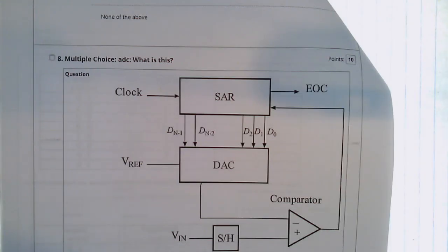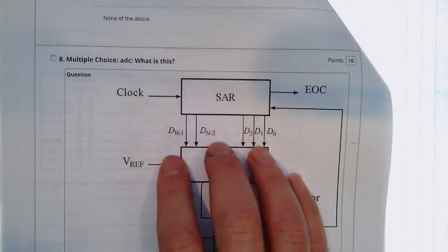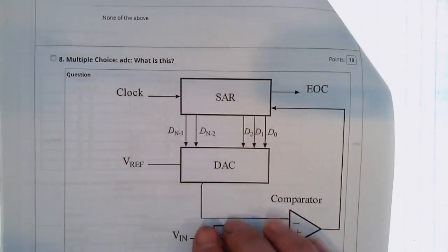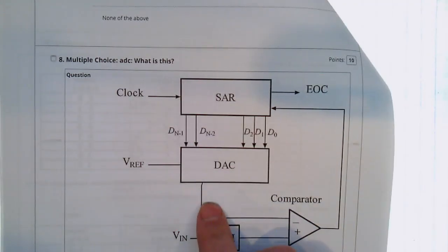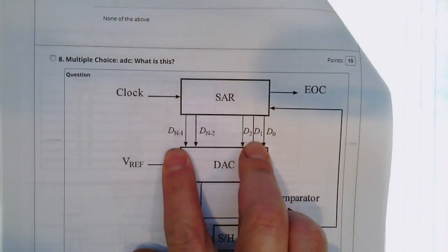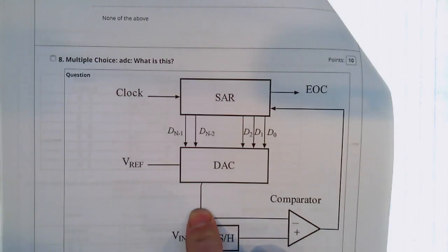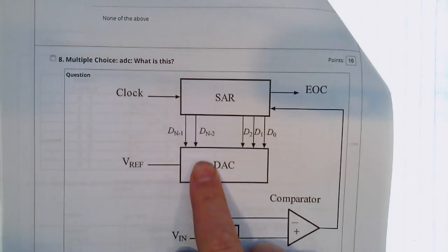That is correct. Yes, that's exactly right. So the digital to analog converter is taking in the parallel digital number in binary and giving us a voltage output. And so if you put in a number that goes from 0 through, let's say, 255, you'll get an output which goes from, let's say, 0 to 5 volts. That's what this stack does.